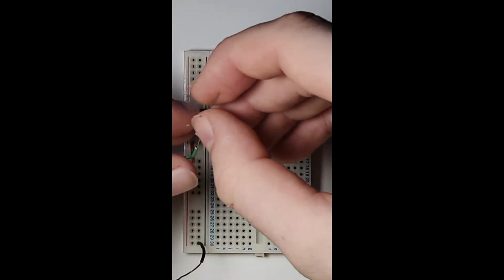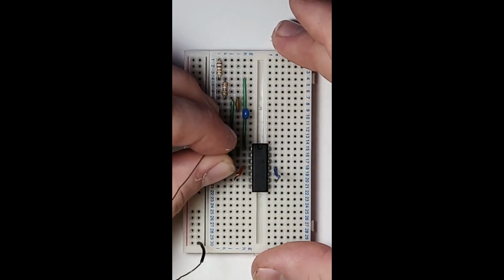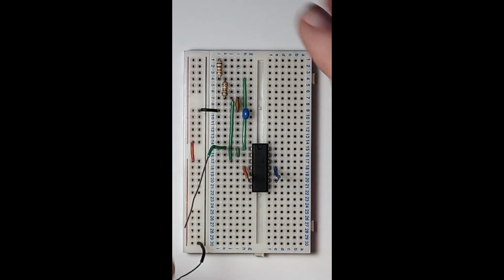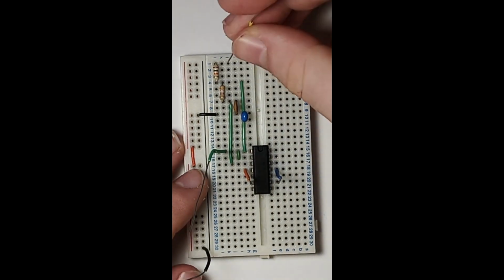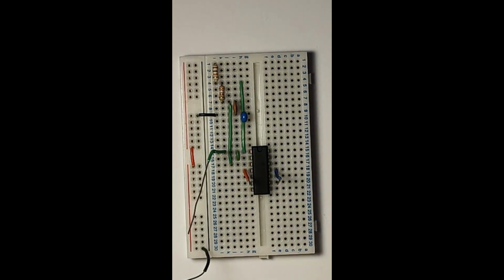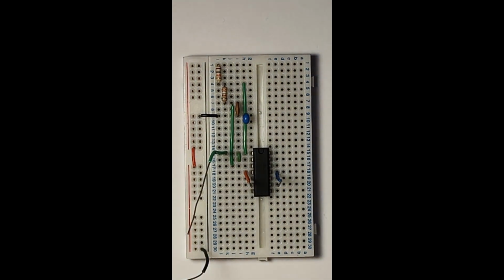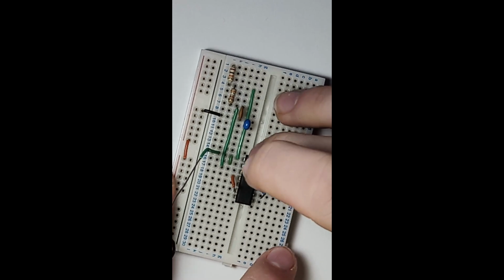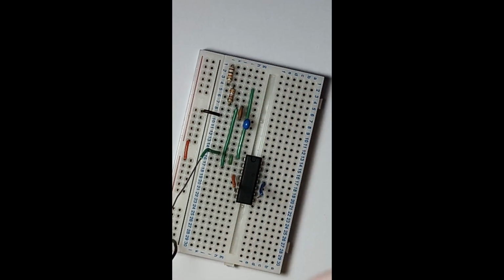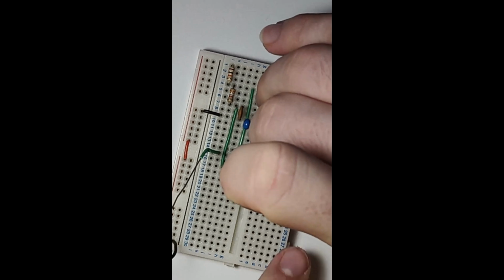So now if we stick this green wire here, we have the output for our Sallen Key, with the input line being right here. It's a functioning Sallen Key. The only issue I was getting when we were running step response was a slight jump at the start of the step, and then it would flatten out. So to fix that, I simply added a buffer amp. All that takes is to short the output and the negative input, like earlier.